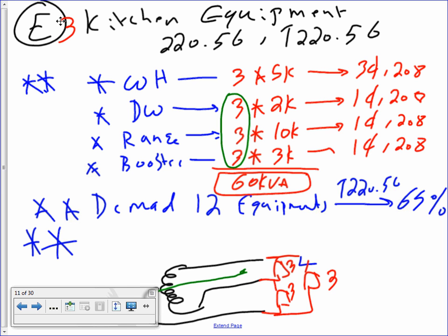How do you get single phase 208? You take just 2 hots. That's all. If you take 3 hots 208, that's 3-phase. Okay. Add them up, 60.